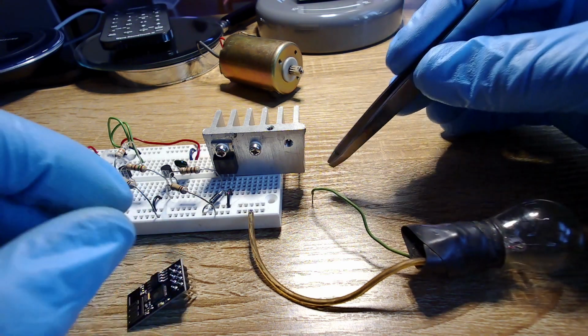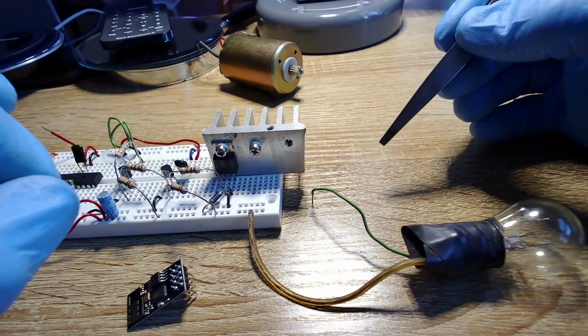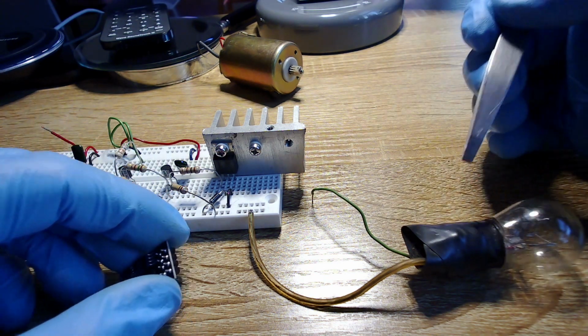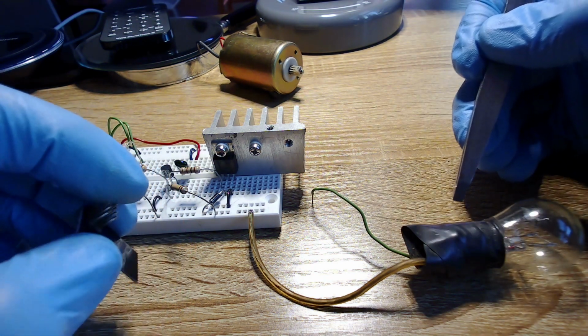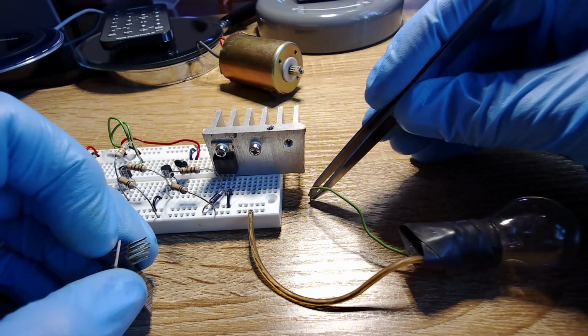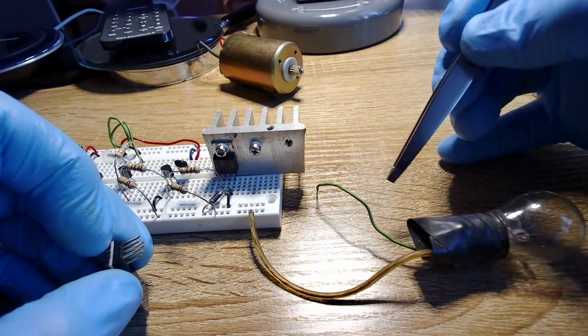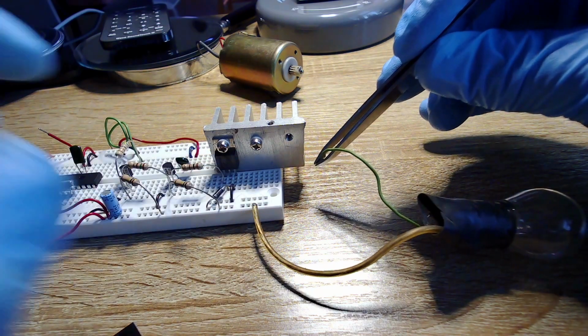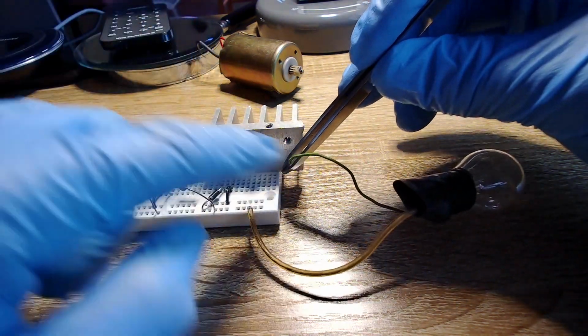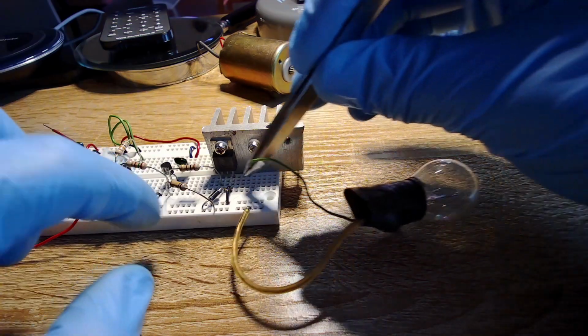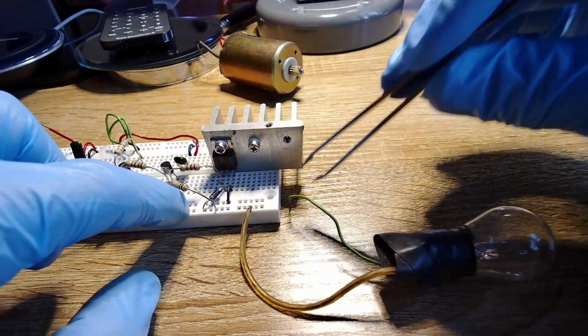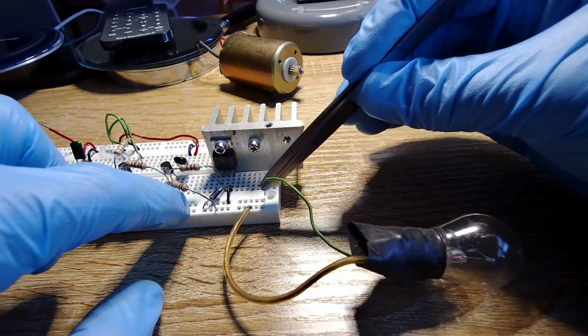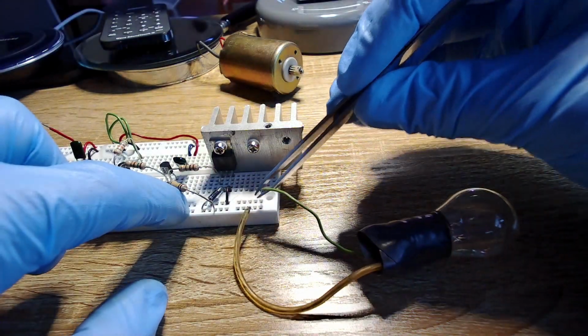Or, for example, a more typical example is the heater coil inside of an oxygen sensor. Typically, the computer will run a current through, and it looks at the other end, as long as there's no current flowing. See, as soon as there's current flowing, you won't have 12 volts here, right? Because if I ground this, obviously this cannot be 12 volts anymore.